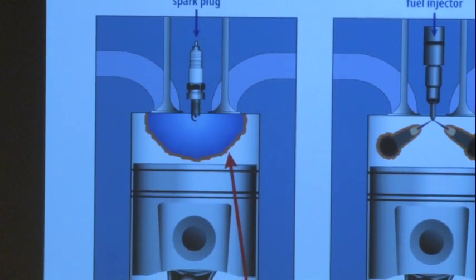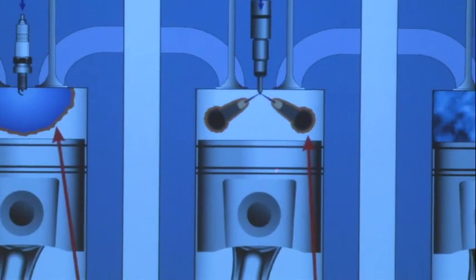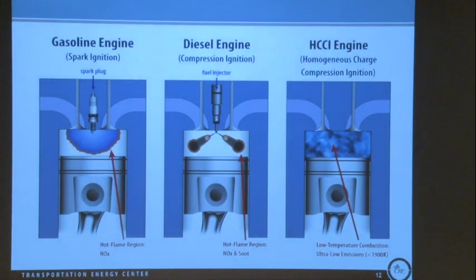And then the other idea is using compression ignition, where you compress the gas mixture, and then you inject through high pressure injection systems the fuel into an isentropically heated ambient, and sometimes you've got exhaust gas recirculation mixed in with the ambient, and then it auto ignites. Usually that ignition starts at relatively low temperatures. These are high pressure engines at 40 to 100 bar.